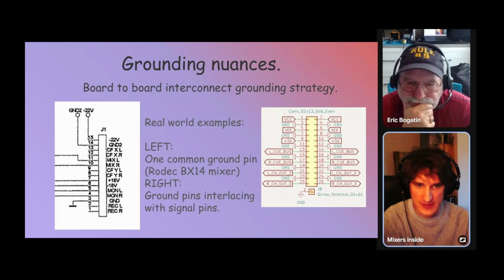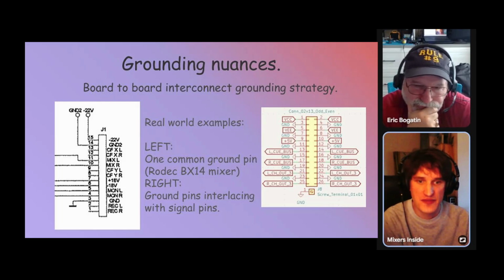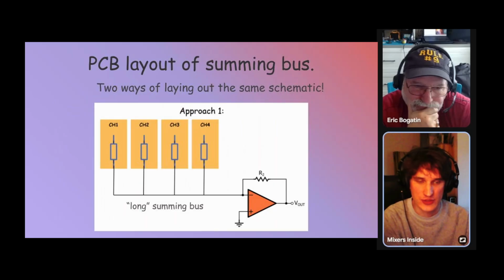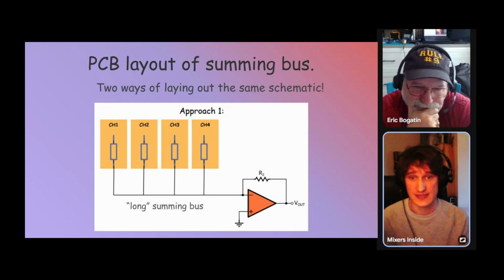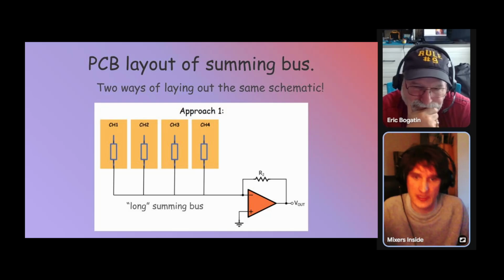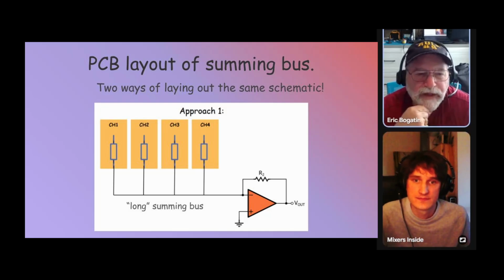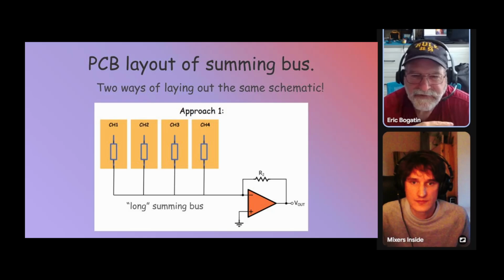But what happens if we plug the signals via summing resistors to those nodes, and those nodes become summing nodes at ground potential? Does it justify this design choice, and can it prevent this crosstalk we were talking about?